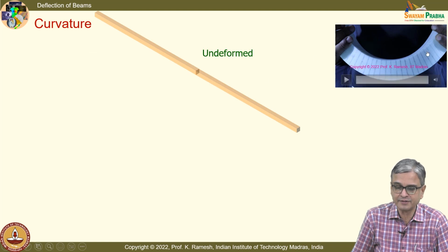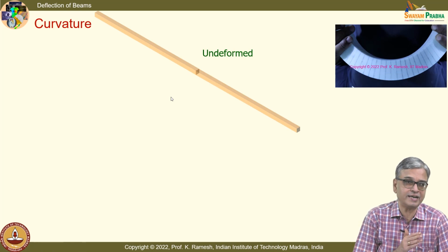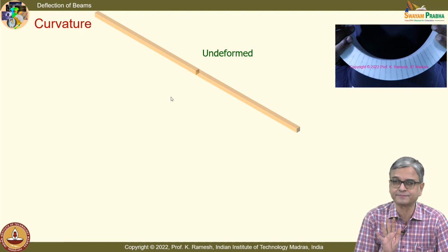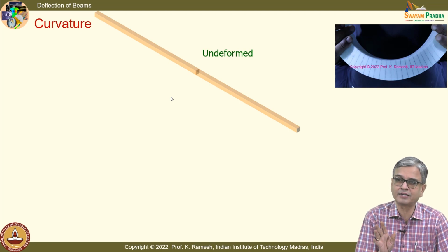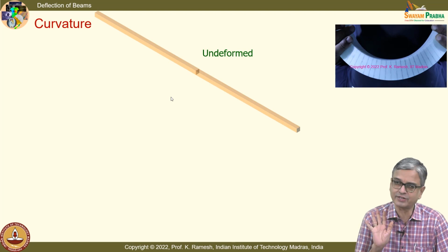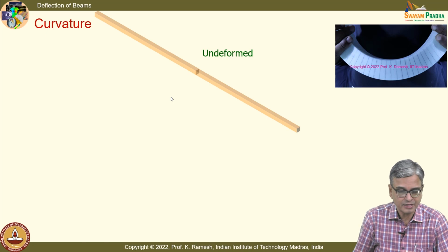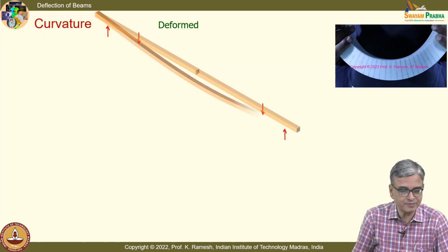And you have the beam bent. And like we discussed in bending stress, here again all the equations are developed for pure bending. Simply use those equations for any other nature of loading on the beam. Look at the bending moment, take out the bending moment value and use it in your equations. So, it is an approximation. We do only engineering analysis. And once you have the beam subjected to 4-point bending, this section experiences pure bending.